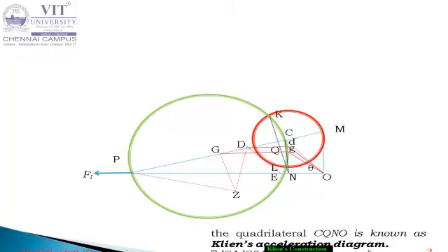The entire connecting rod mass will be concentrated at G, so the acceleration is assumed to be acting at G. So we have calculated the magnitude and also the direction, if the mass is concentrated at G. OG is the line of action. But the resultant must pass through E and it should be parallel to OG.